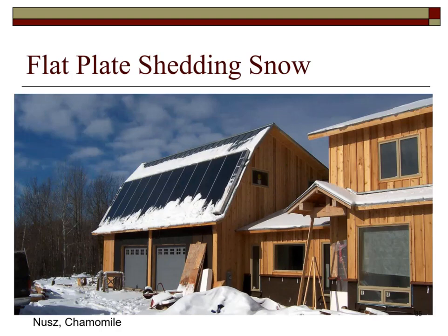This demonstrates flat plate solar thermal modules in a snow environment. Flat plate modules have the advantage of melting snow. If they are at a slight incline, the module will begin to heat up and the snow will begin to melt and slide off. Evacuated tube collectors do not have as high a surface temperature due to the absorber being in a vacuum tube. Therefore, evacuated tube collectors do not offer the same advantage as flat plate collectors to melt snow.